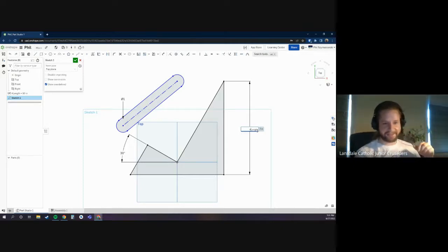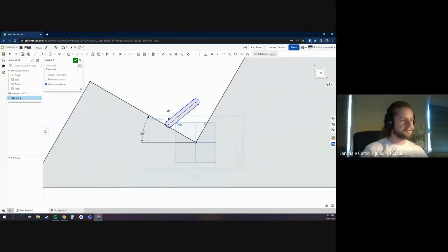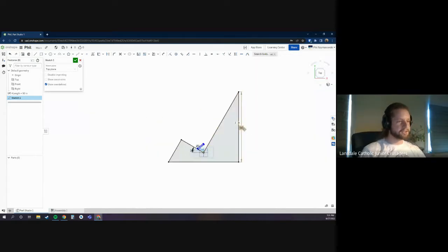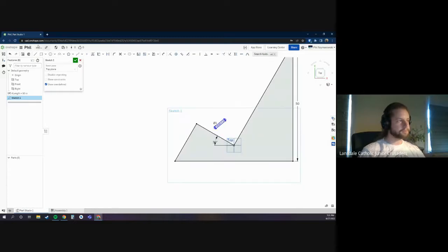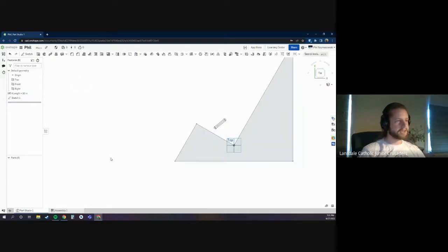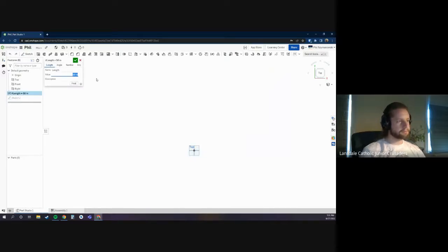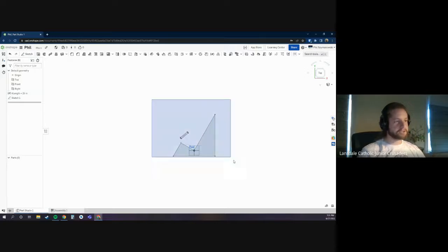Pound sign length, and you hit enter, and now that dimension is 50, which is what the variable is equal to. If I leave the sketch, I can now change this 50 to maybe 25. Now it changes the scale of that object. This side's now 25 inches long.